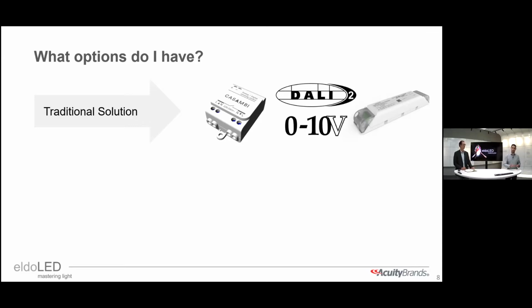And where Casambi says we're following that DALI 2 standard, you can use any DALI 2 driver available in the market. You connect them together, you match the profiles, and it should work. Because we stick to that interoperability standard, using DALI 2 as a reference, that should work out of the box. But that means that you need to prepare the units and the drivers in the same way.